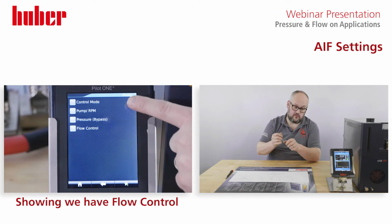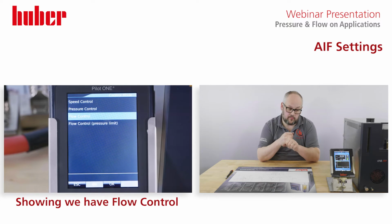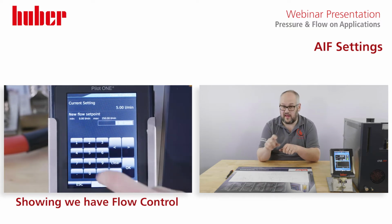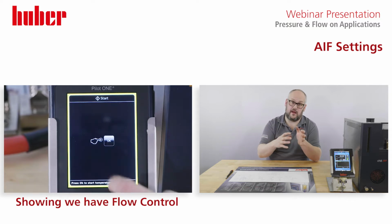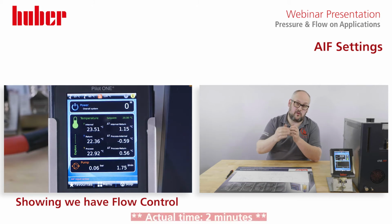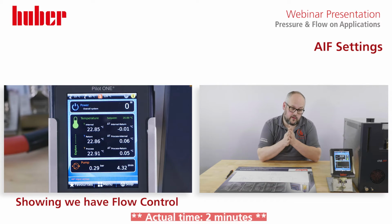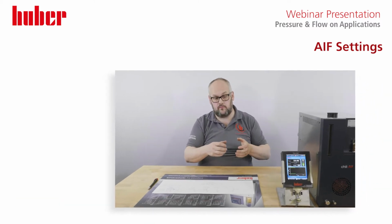And in the case of flow control with pressure limit, in pump control pressure, you can set half a bar if you're worried about it, and the unit will only operate up to half a bar. If your flow rate is in that range, it'll hit it. If your flow rate is outside of that range, it will only operate to half a bar. It won't push it any further than that. So this is quite valuable, that we can do this with a simple setup like this.